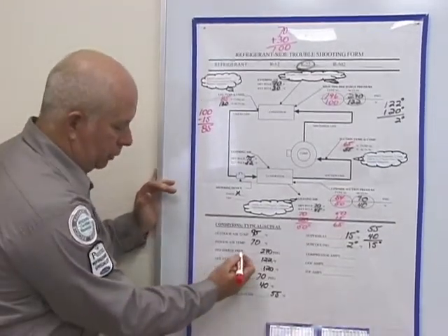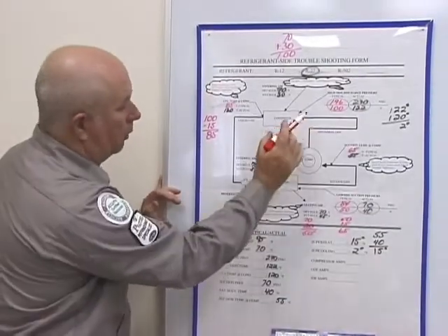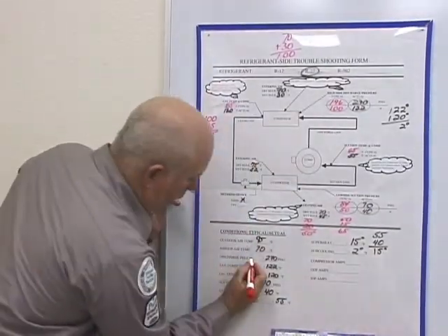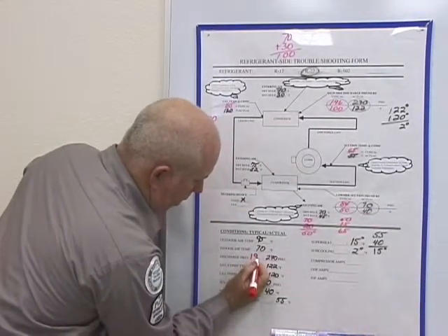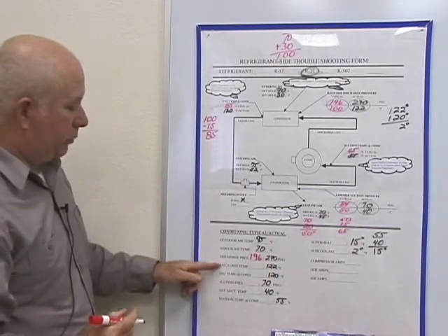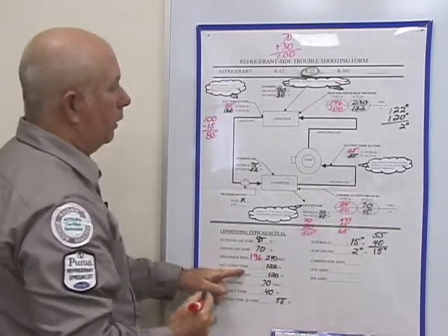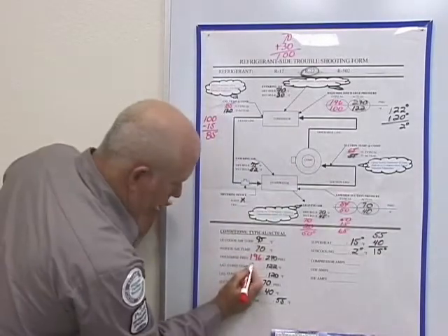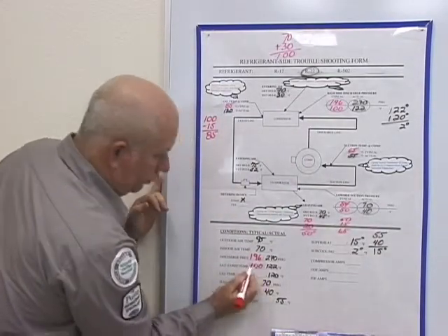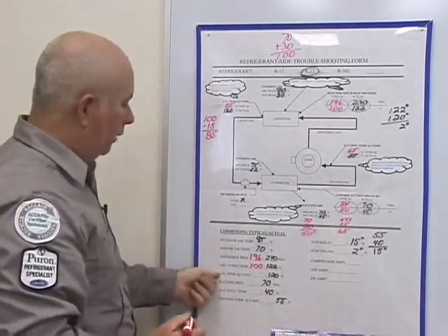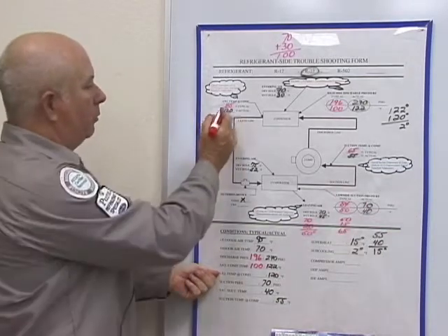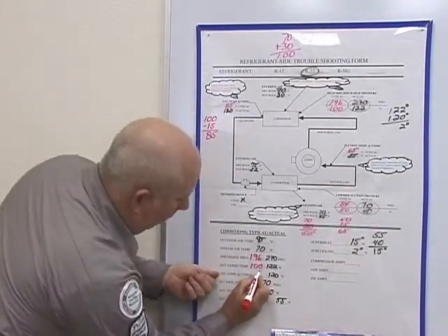We go back to our discharge pressure. We come up here, our discharge pressure for our typicals is 196. Saturation condenser temperature, again, it's 100 degrees because we use the PT card to convert it. The liquid temperature at condenser, we come up here, 85.